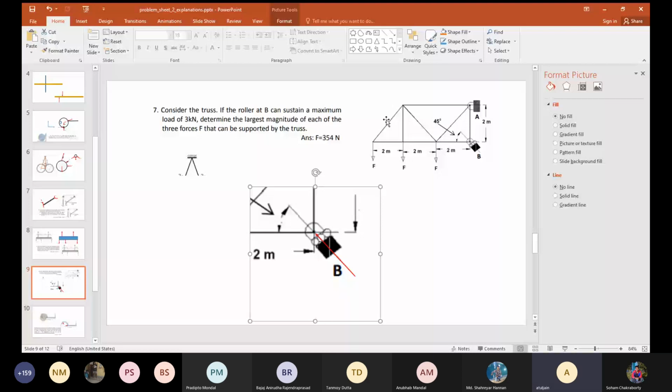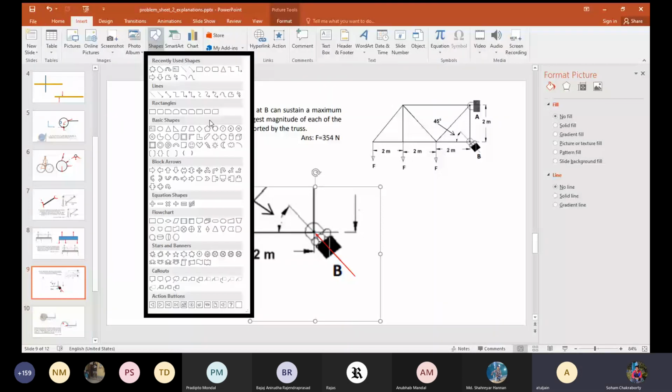So the triangles you have to consider in truss are only the upright ones, no? For this problem, you can neglect the inner detail, just draw the free body diagram of the outer boundaries. What is happening inside individual members is none of your concern. This truss is just distracting you, so let me redraw another figure. We can only consider the outline also.